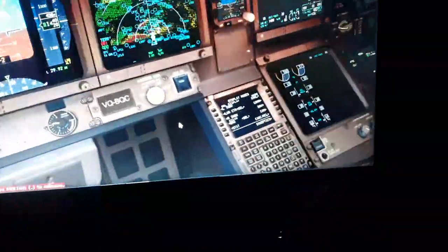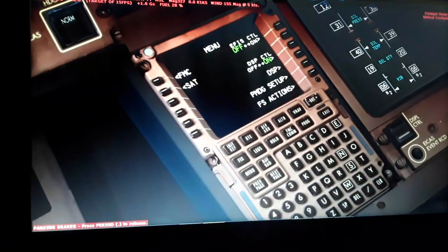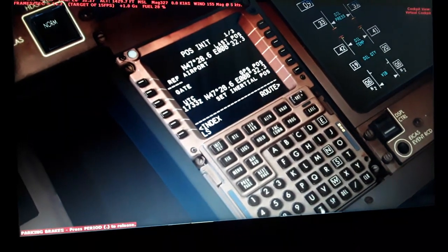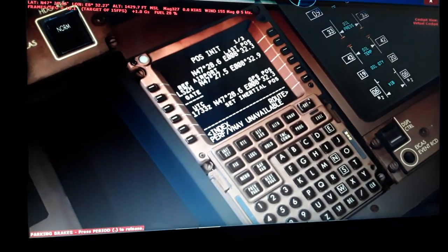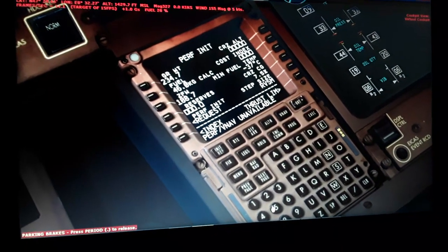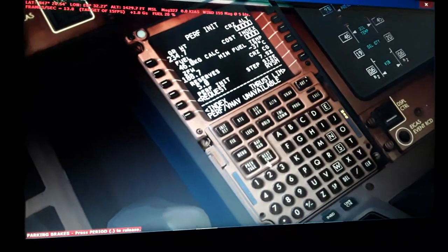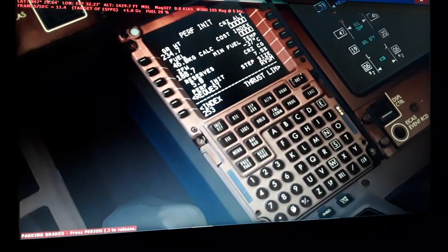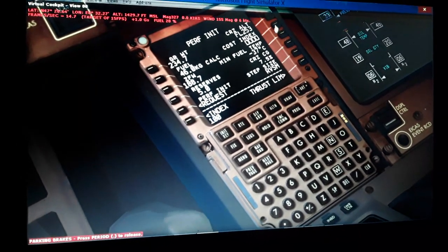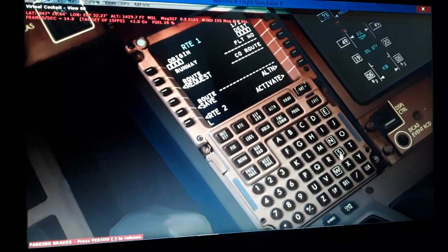So we are ready for starting the aircraft. So we left only one last step here. Menu, FMC, position initialize, LSZH, the reference airport, 0 fuel weight, reserves 5%, cruising altitude 35,300 feet, cost index 100%, minus 37, decrease. LSZH,